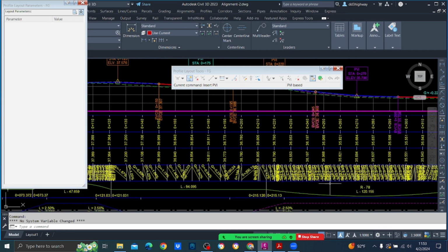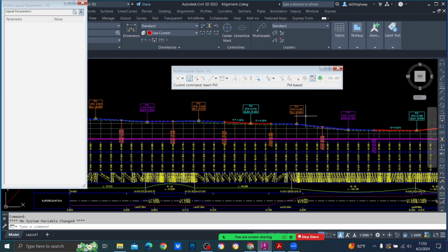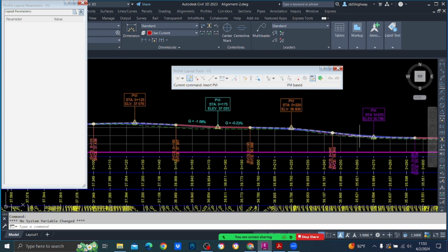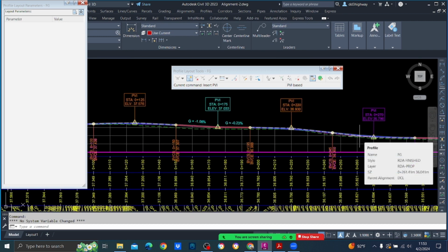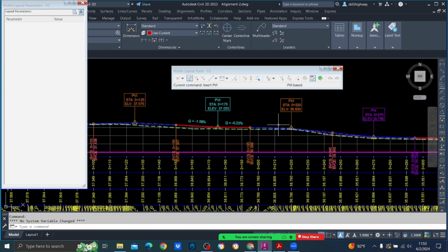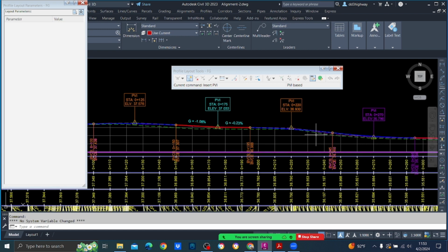If your horizontal alignment is going at 40, is there any necessity to make this 50? Just think about it. Horizontal alignment is catering only for 40 kmph. Then your vertical alignment, you are going to provide it for 50 kmph with the high fill. Is that required? No. So you can reduce the vertical also to 40.